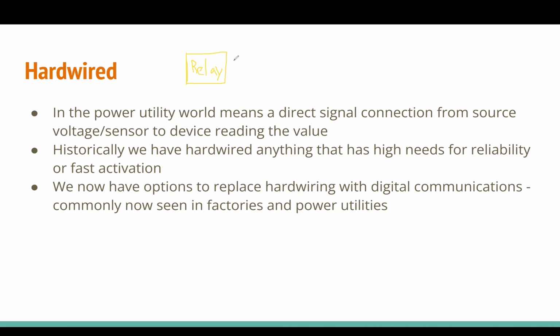And so if we have a relay, then we would have something like out in the field like a CT. So I'll put that here as a CT, or a current transformer. And if we're taking the actual data from this CT and running it back into the relay, this is going to be some sort of a voltage waveform on this line.